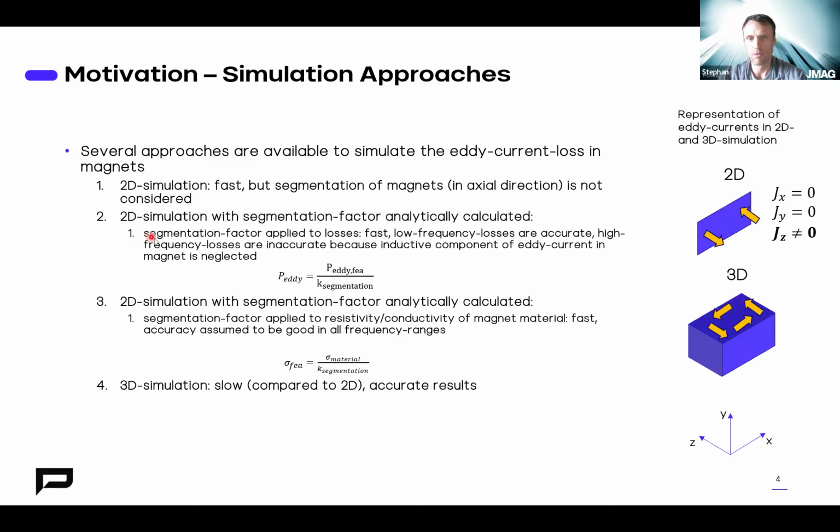And that's why there are several publications where analytical segmentation factors are calculated, or how the processes are described, how we can calculate this kind of segmentation factor. As said, I want to use these approaches to recalculate the results of a 2D simulation to a real 3D loss value afterwards. And this segmentation factor can be applied to the losses we have simulated with a 2D simulation.